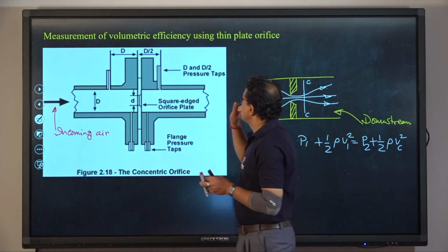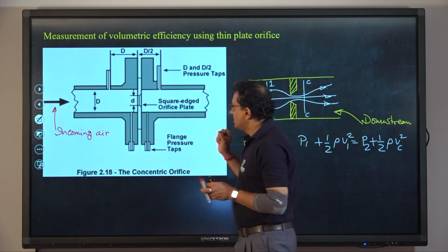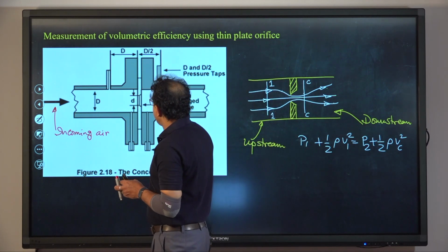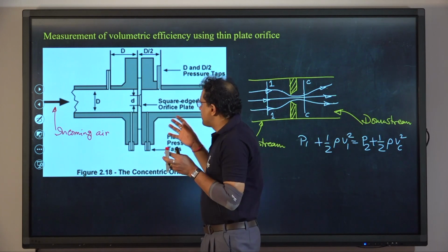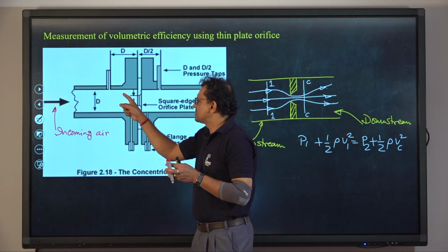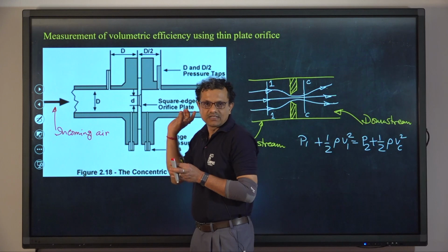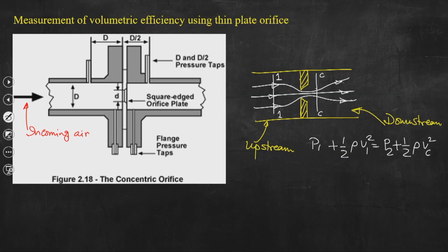So, this is a thin plate orifice meter, and you can understand two pressure taps are there, and from these two pressure taps we can measure the pressure drop as the flow is passing through the orifice meter. Now, if we apply the mechanical energy balance equation, you can understand. So, this is, in fact, I can write this is Pc, and then we can write that Vc